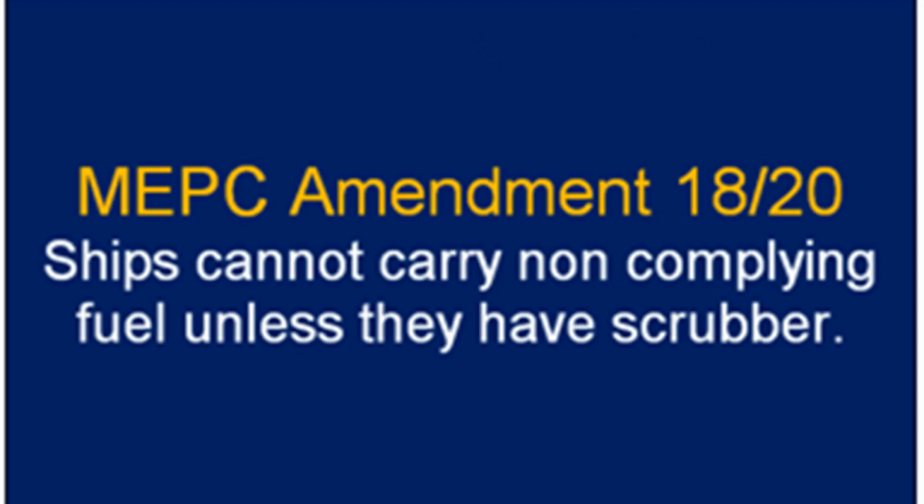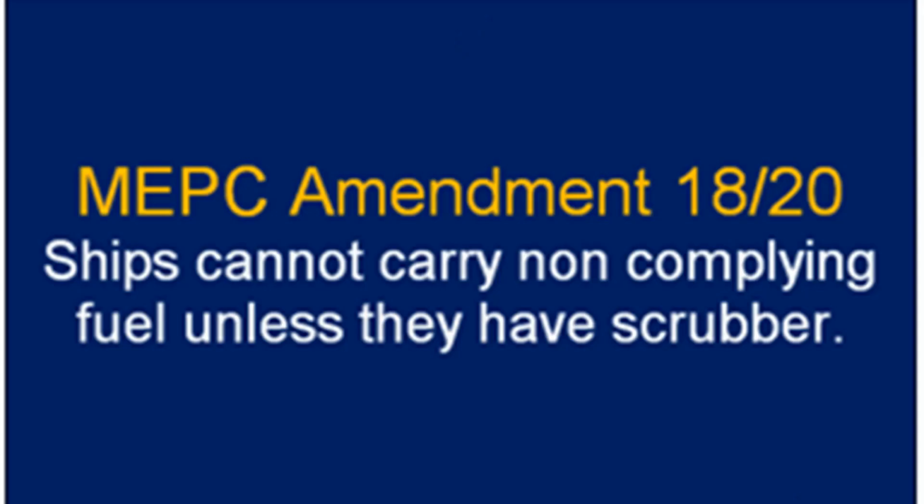In October 2018, MEPC adopted an amendment which means that ships cannot carry for combustion purposes fuel that would give out SOx which is not within the limit unless you have a scrubber. This amendment entered into force in March 2020, which means that thereafter the ships either have the scrubber which is doing its job of controlling the SOx emission, or you're using a fuel that is deficient in sulfur.